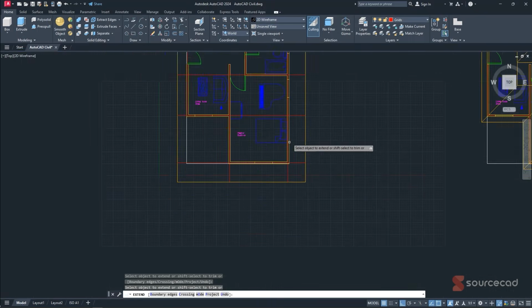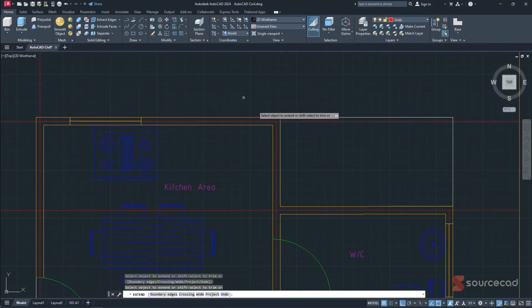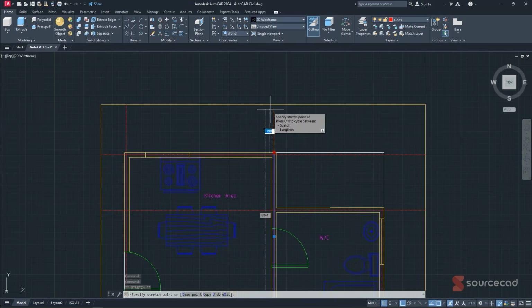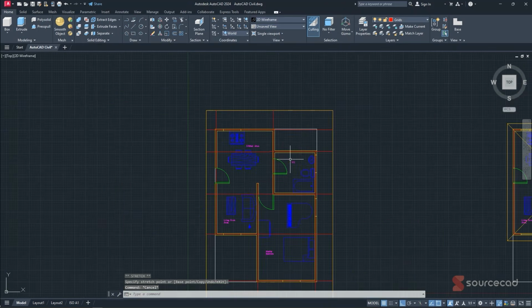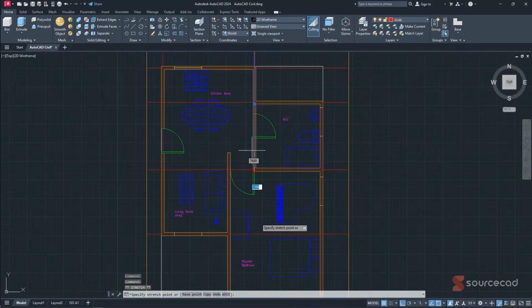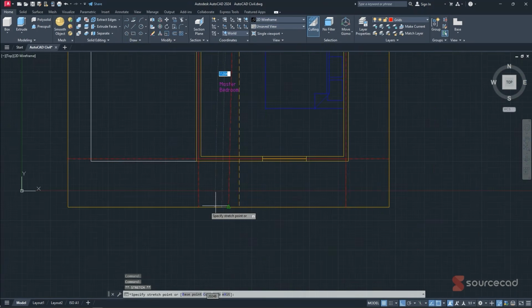And that's the way we simply extend. For the lines that are still missing, just simply select on them, click on that and extend it simply by tracing from this point up to that point of intersection there, and this line as well from this point all the way down up to this point of intersection there.